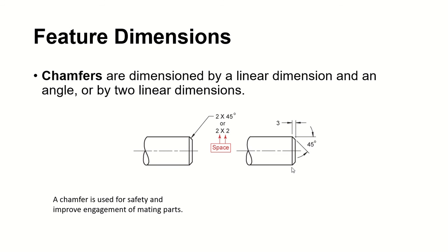Of course, when you look at it from here, it's going to be like you tilt the bottom chamfer to show 45, okay? It's pretty easy. It's like this plane and then that plane, okay? So when you see, you know that you can extend that plane out, on the non-material part. This is your material. So your material part is this first plane and the second plane is 45 degree. Your first plane and the second plane has 45 degree. Okay, so you can either dimension this way or this way for your chamfers.